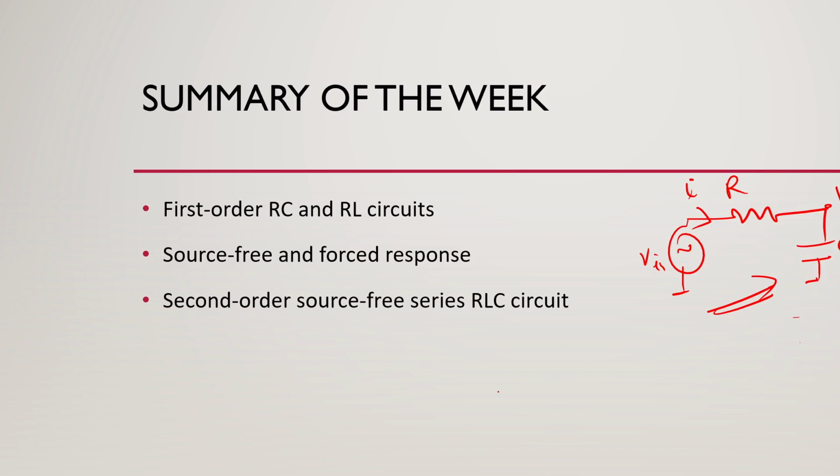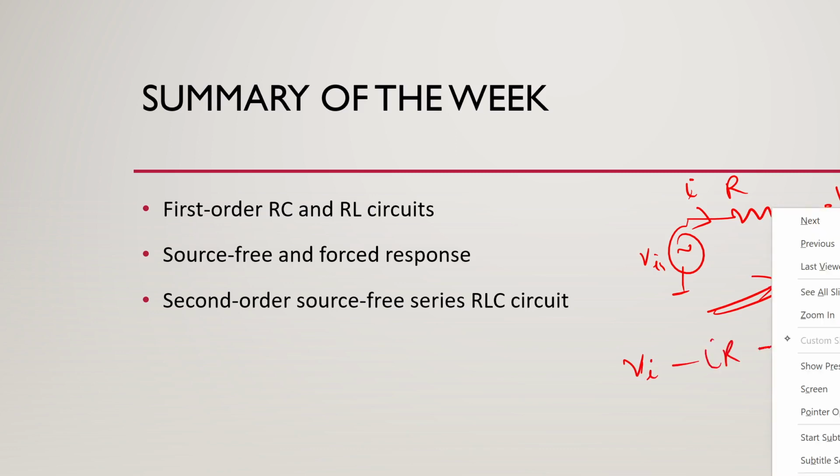Yeah. So let's write KVL around it. It will be VI minus IR minus V naught is equal to 0, right?